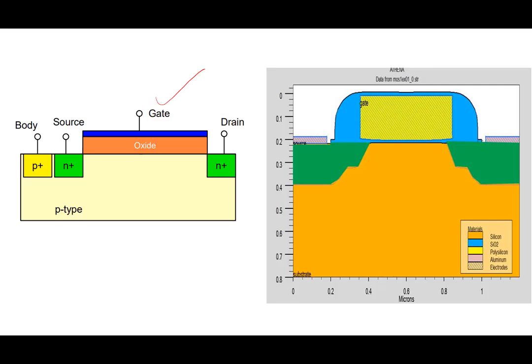Now this is also a schematic, and it's a geometrical drawing. Everything is square, as you can see here. This is a more realistic picture of the MOSFET. As you will see later on in the course, this is also a conventional, let me say, planar MOSFET, which has been with us for a long time. Planar means everything, source, drain and gate, are roughly on the same plane. Of course the gate is a little bit above, but nevertheless one can talk about a planar MOSFET with everything being in the same plane.